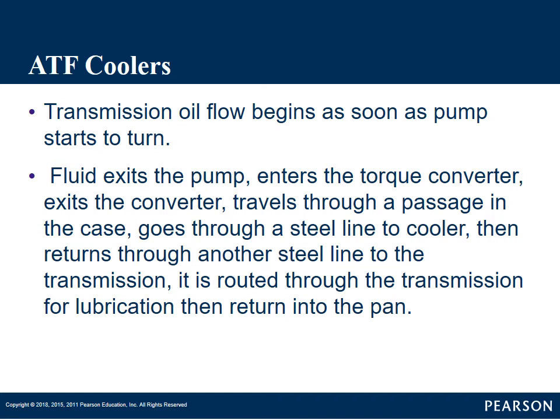When we're talking about transmission coolers, the only way it cools is if we can get that transmission fluid from the transmission to a cooler. Transmission oil flows as soon as the pump starts to turn. So when you start that engine, the pump in the transmission turns and it starts pumping fluid. The fluid exits the pump, it enters into the torque converter.